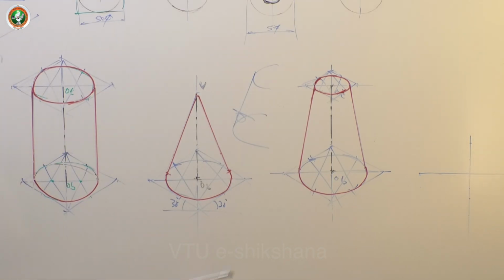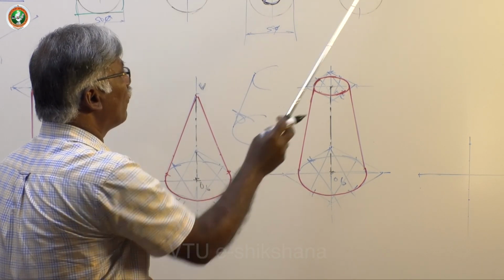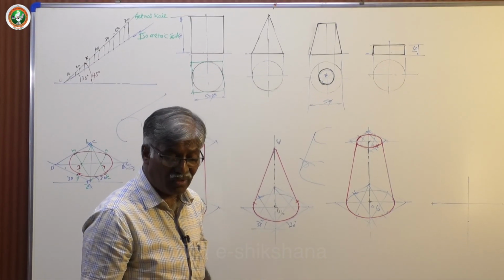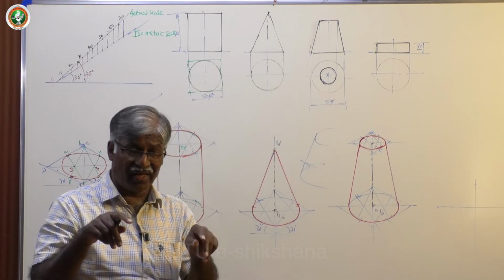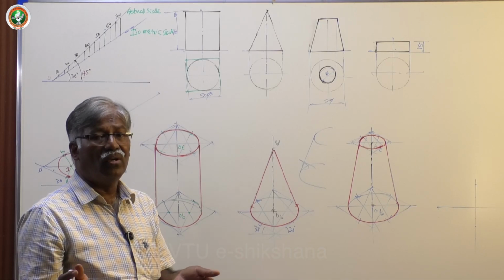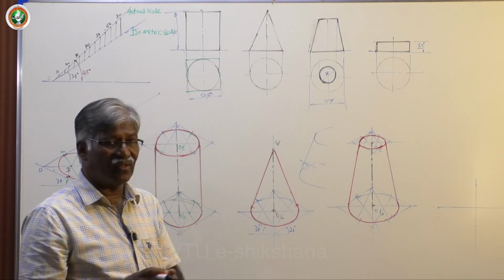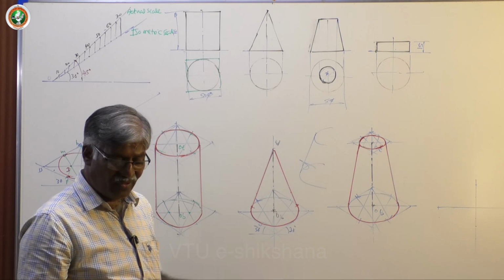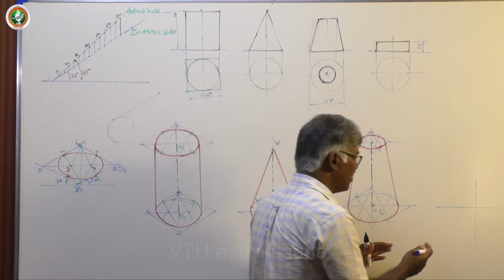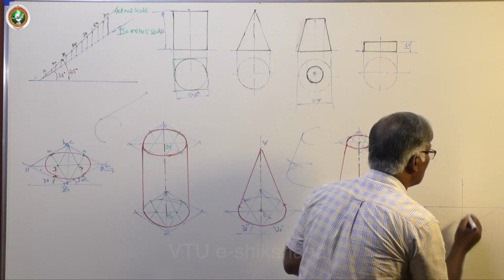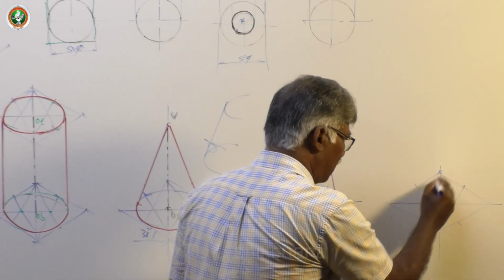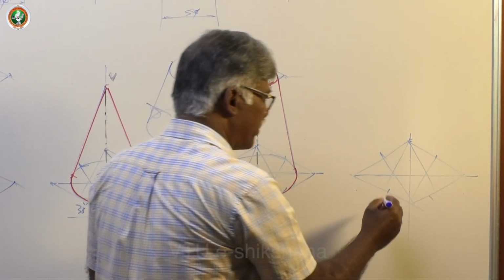That's all. Then last one is the block. This block is having a thickness of 15 and then diameter of 50, say. First you have to create the block. Unlike the square, where I drew only 3 lines or the outer visible lines, here I cannot do that. I have to create 2 ellipses, one with the top face and the other one base, and then join them. We will show you how exactly that works. Now you must do it carefully because you should have patience, otherwise it will go wrong. Now keep this with very light line, then mark, draw lines, then 4 centers method, complete.